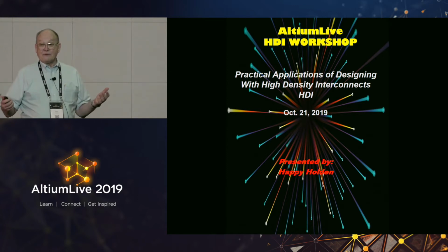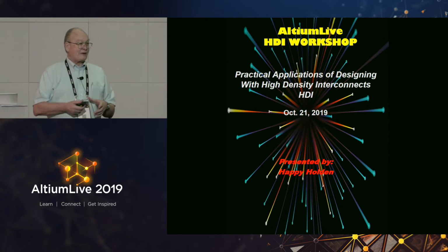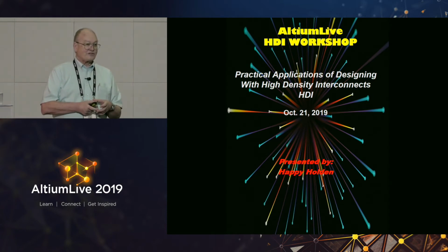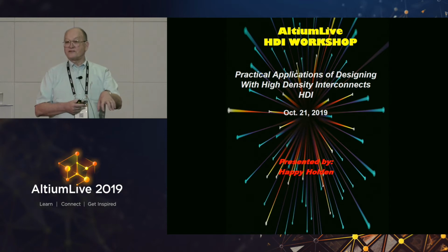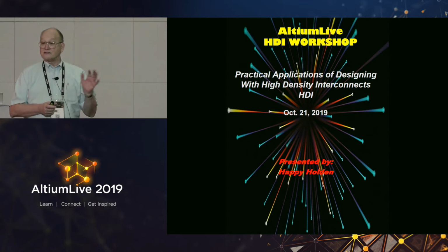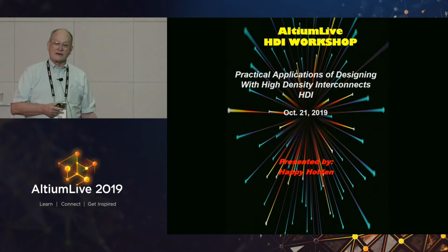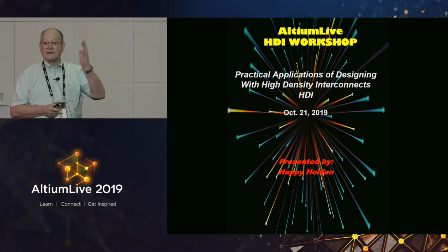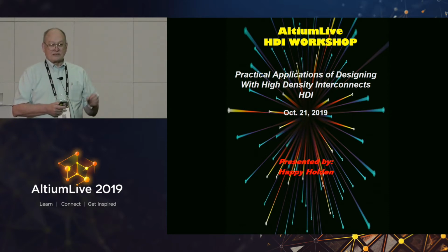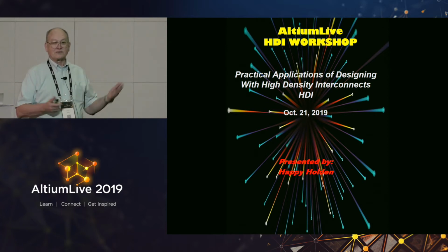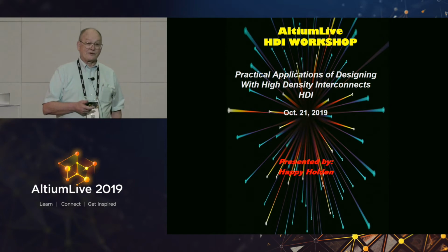And because the semiconductor people don't like to pay for transmission lines on their packages, they use up the critical length, so that when you buy the chip, you have to be 100% transmission line on your design, even if the clock is slow, because it has nothing to do with clock rate, it has to do with the rise and fall time. And these tiny transistors turn on and off very rapidly. So consequently, they're transmission lines whether you want them or not.